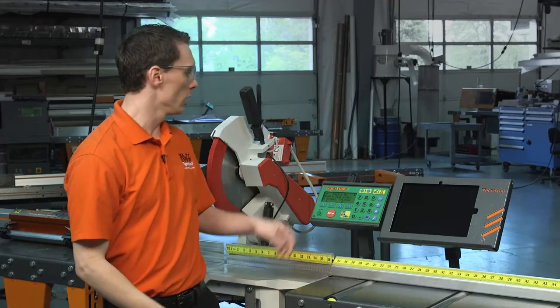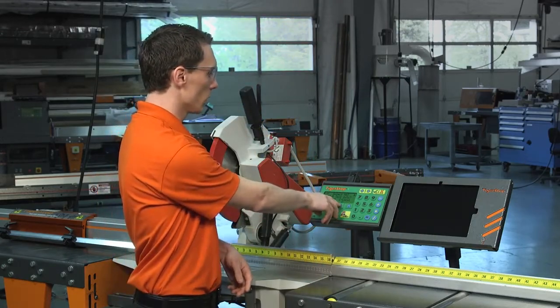The next option is going to be your head and tail cut. There are 2 options for that: global and local. Global is just a global parameter that you would set in the part list menu. So if you're doing the exact same head and tail cut every single job that you run, it's recommended that you just set your global value and just select global every time. However, if you're looking to do a custom value depending on the material that you're cutting and so on, then I would suggest select local. For this video, we are going to select local.